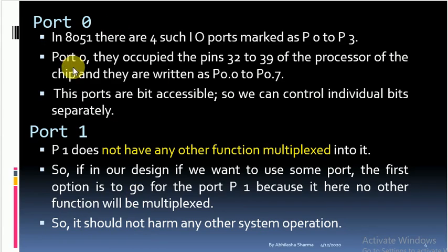Since all ports are IO ports, they are used for 8-bit read and write operations. These are general purpose ports, and all the ports of the 8051 are multifunctional and multiplexed. Port 0 also acts as the low byte address and data bus for external memory design.